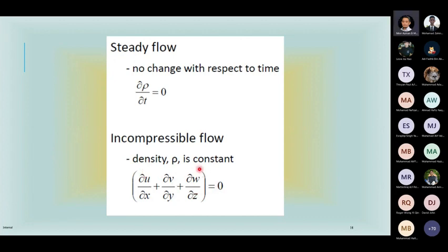So by this continuity equation, if you have a flow velocity distribution, you differentiate the u velocity with respect to x, the y direction velocity v with respect to y, and the velocity w in the z direction with respect to z, and it will always equal 0. So if you apply this derivation to your flow profile and it equals 0, then it's incompressible flow.